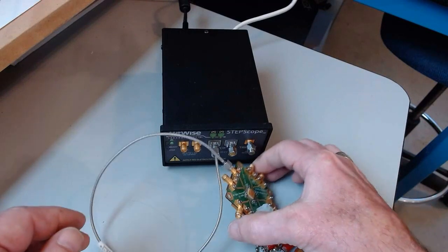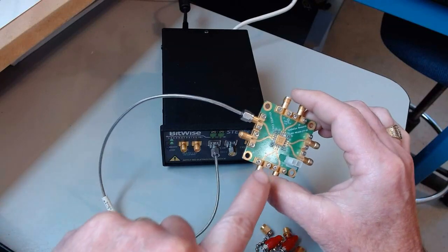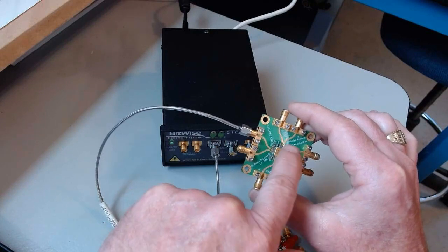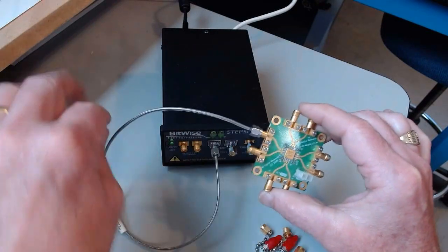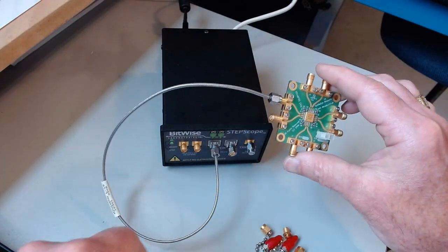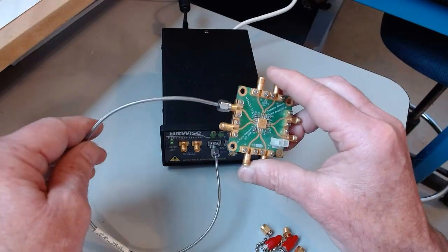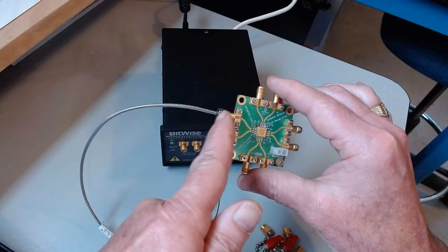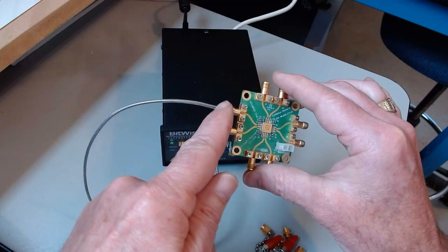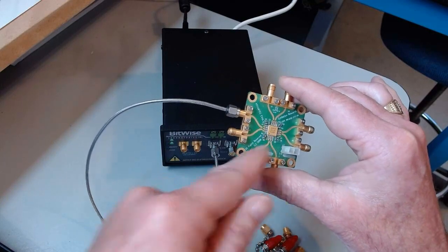So the measurement I'm going to make is of a small test DUT here, and specifically I'm interested in getting the return loss in the integrated circuit, but to get to it I have to mount it on a board, I have to connect to it. I have a 16-inch cable here I'm going to use. I'm making single-headed measurements, I might point out, so I've terminated the unused input of the differential pair. So I'm going to set my reference plane here at the end of this connector, of the cable, and perform that reference plane calibration, and then make measurements of the return loss.